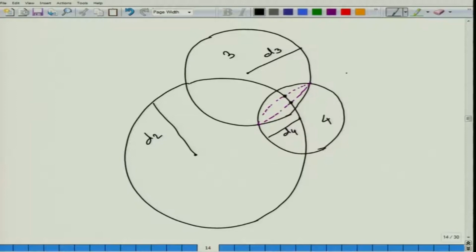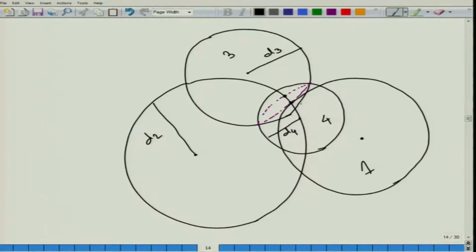Now, if we took a fourth sphere, we know that we are at a distance of d1 from the position of satellite 1. So, we would now be able to say that out of these 2 points we are not at this point, but we are at this point. Now, we generally require only 3 spheres because the fourth sphere is the sphere of the earth. Now, this would give us our position.